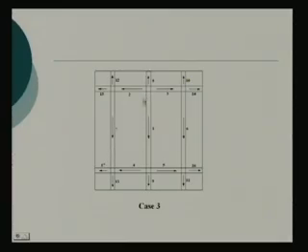This is 1, 2, 3, 4, 5, and then we went to 6. Then when this side, then came here. So, you see, after the 7th welding, this entire central part of the plate has become rigid, and then we again came back to the middle, 8, just opposite 9, right.